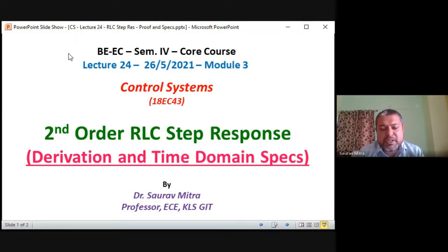The first system was undamped, zeta is equal to 0. We had found that the performance is like an oscillatory movement. Then we had increased the value of R in damping. We increased the damping zeta in between 0 to 1. So for your simulation, you can keep the damping as 0.1, 0.15, 0.2, 0.3. So don't go beyond 0.3, because the lesser the damping, the better oscillation you will be able to see during your simulation of experiment number 5.